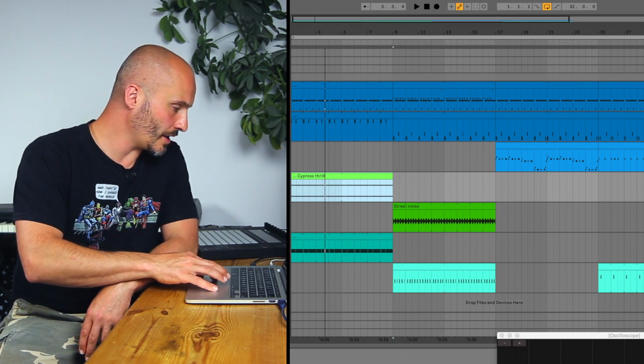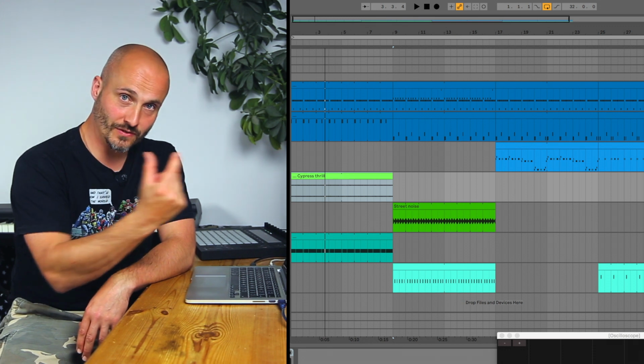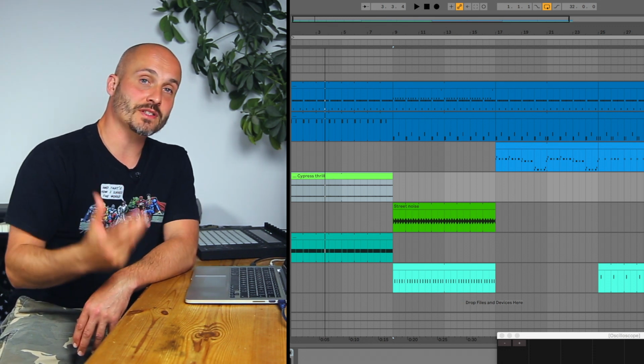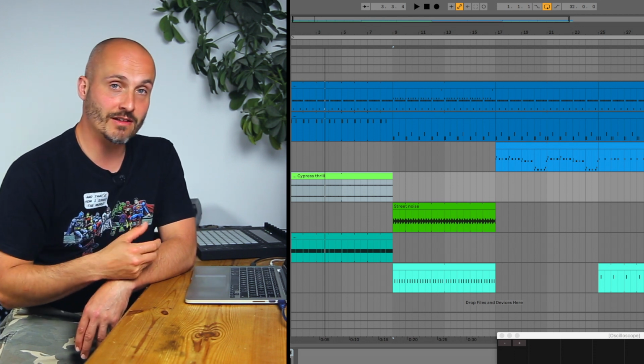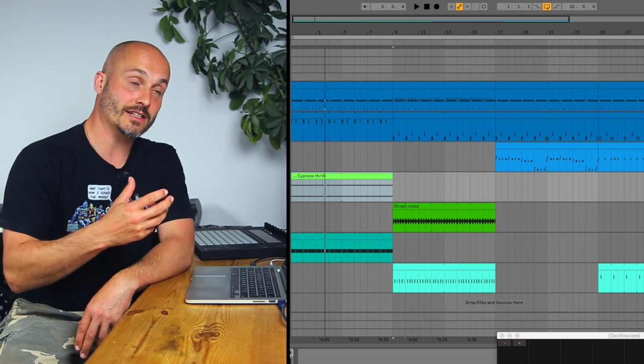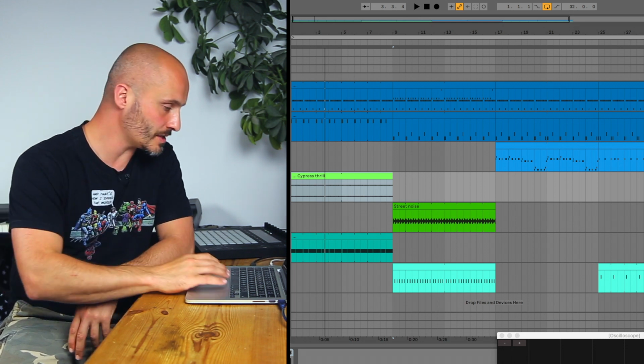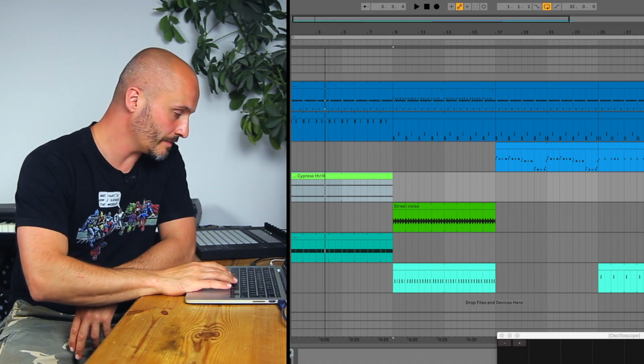If we go for something like overdrive, which has that bandpass filter where we could tune it to work with the sound, we can try and emphasize this background sound in a different frequency area than it actually naturally has, and let the distortion create a new range of frequencies to help that sound come through the mix better.